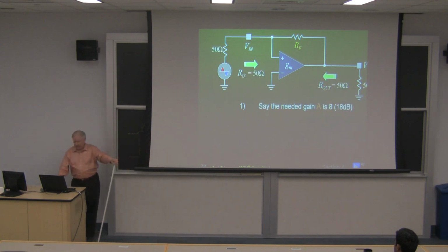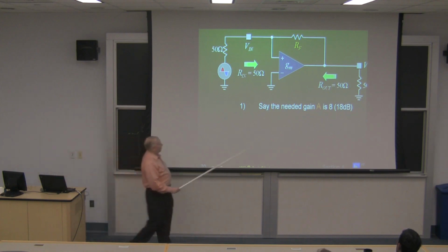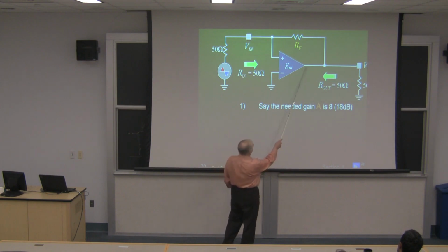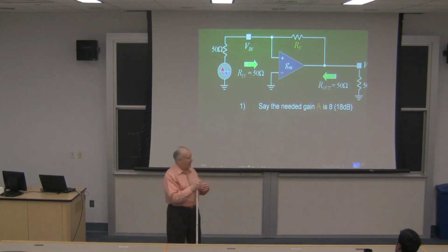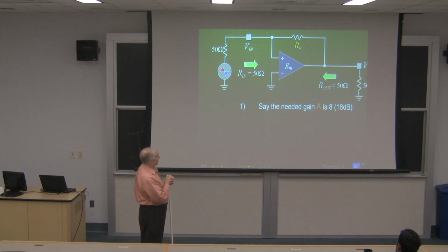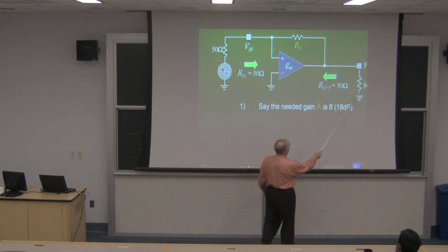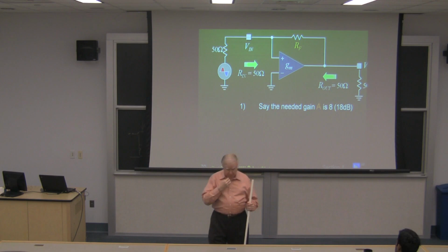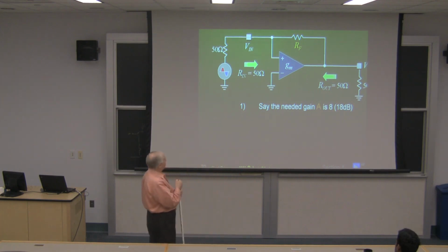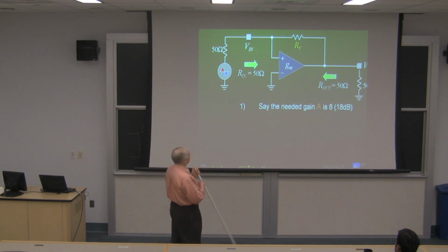So this is just an example of a 50 ohm bilateral match. By bilateral, of course, we mean that we want the circuit to look like 50 ohms looking back in here as well, because many times you'll be driving something that doesn't like to have reflections, or that is upset by reflections. For example, a long cable that is improperly terminated at both ends. Now, if it's well terminated at the load end, there should be no reflections, but usually it's not. And so any reflections that come back here should ideally be absorbed. It could be a filter. Very often an amp like this would drive a SAW filter, and the SAW filter needs to be driven from and loaded by certain very specific impedances, which the manufacturer tells you. And so bilateral matching is often important.